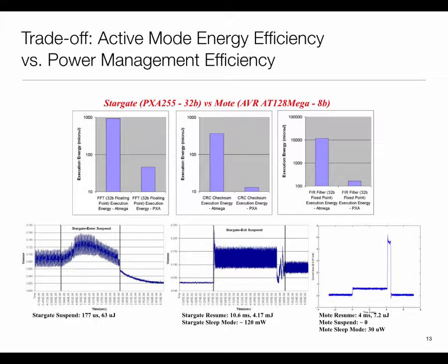So usually what processors do is they provide various kinds of sleep modes. In fact, most modern processors have many sleep modes. They go under the names of sleep, idle, dozing, all sorts of things. And the deeper the sleep they are in, the less power they will consume when doing nothing, but the more time they will take to come back up, because more state is lost.